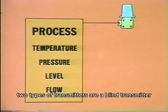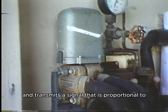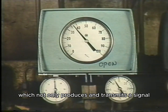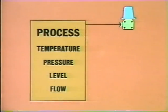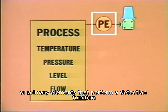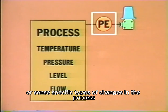Two types of transmitters are a blind transmitter, which produces and transmits a signal that is proportional to the value of the process variable, and an indicating transmitter, which not only produces and transmits a signal, but also indicates the value of the process variable. Transmitters are able to determine the value of the process variable by input they get from devices or primary elements that perform a detection function. That is, primary elements detect or sense specific types of changes in the process.